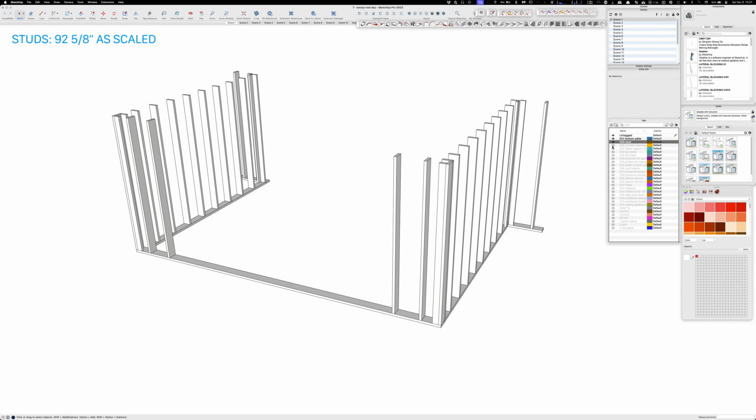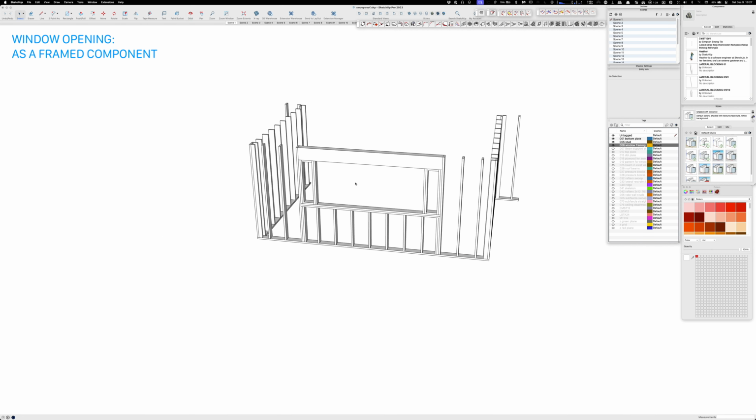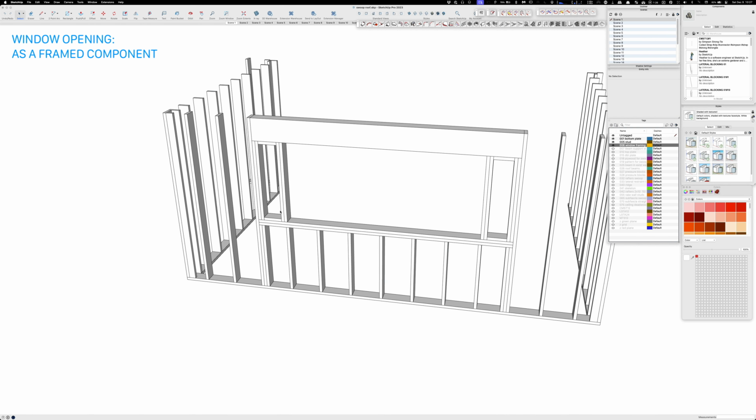Studs. Everything needs studs. All walls need studs. And then here's something that I learned from Larry. The actual window opening is here. And often when he was framing, and he started back in the mid-60s, in order to prevent the sheetrock from cracking around windows, which sometimes happens, they would just extend the header to the next stud and then fill in.